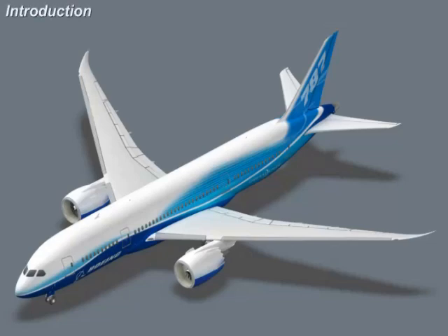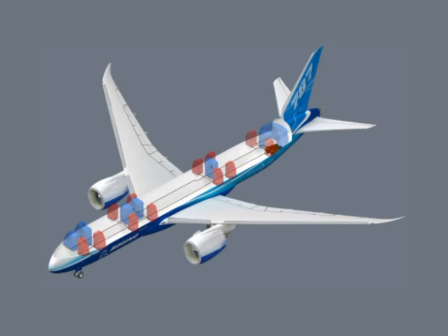In this module, you will operate the Cabin Attendant Panel, or CAP, cabin controls to identify the normal and non-normal indications. The Cabin Attendant Panels control and monitor passenger systems in the cabin area. The three CAPs are at flight attendant stations near passenger entry doors, 1 left, 2 left, and 4 left.